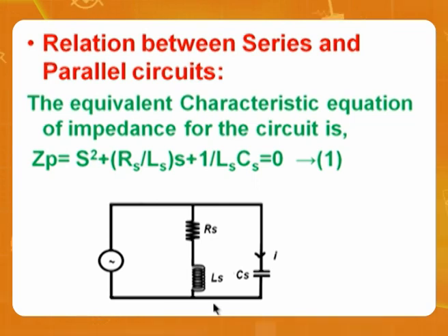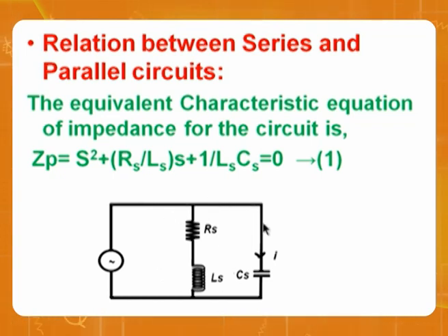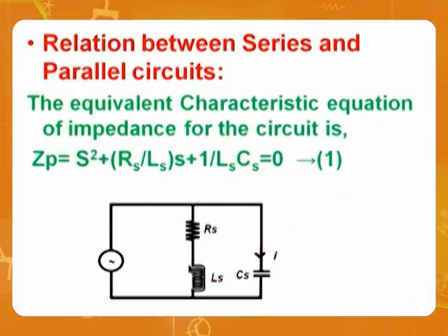So now I am going to give a very interesting conclusion, because this is more practical, whereas the previous one is theoretical, because nobody will connect a resistor in series. Even in series resonance, please understand, R is always part of L. Only for our theoretical analysis we took it outside. Otherwise, nobody will connect a resistor separately. The resistor is always in series with the inductor.